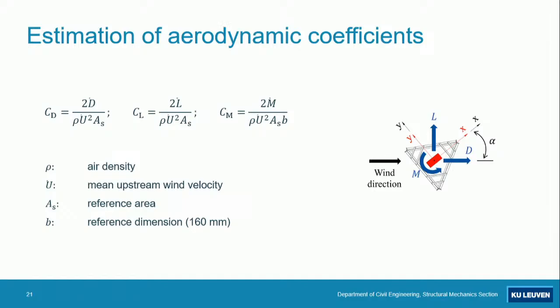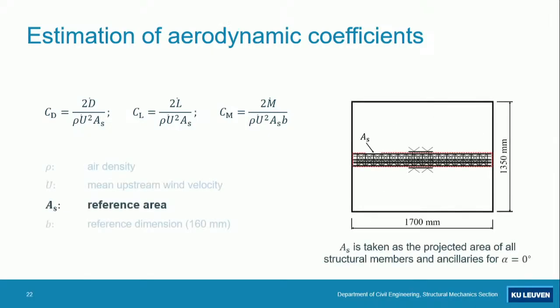So from these forces, we've also estimated the aerodynamic coefficients, with the expressions presented on the slide, with also a reference area which was considered the one for an angle of attack of 0 degrees, so one of the orientations of the sectional model, which was then maintained for all the other angles to compute these coefficients.